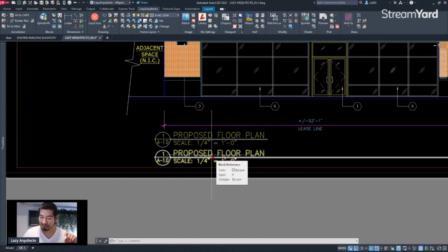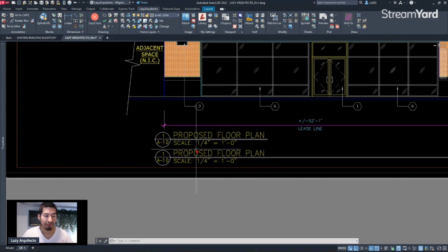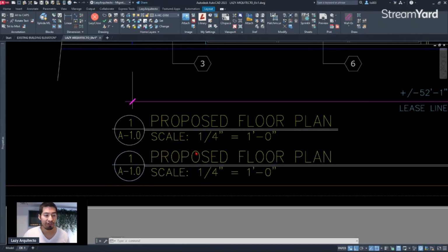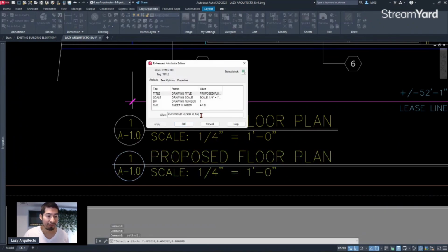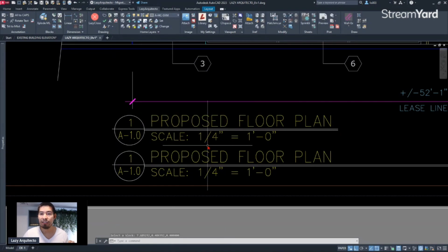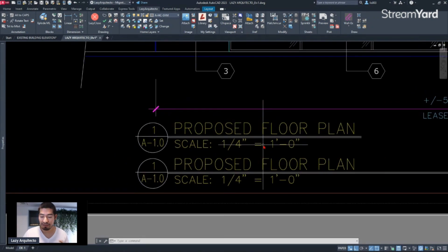So the third thing was the idea that my friend was populating or adding information to his block manually, right? But we could automate that process using something here in AutoCAD that is called a field. A field is basically a way to automate the input of data here in AutoCAD. So we have to set it, and then we don't have to remember again to put that information in. Let me give you an example.